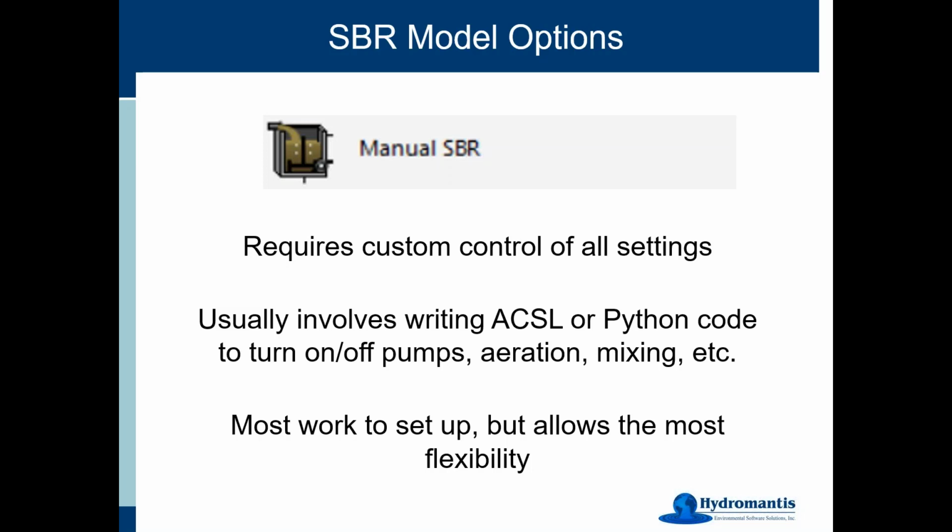The one time that I remember this was actually really handy was a particular project that I worked on that had 3 SBRs in parallel, and it flipped the loading back and forth between the top and the bottom one. And the one that was in the middle had a whole different schedule that involved taking overflow from the top and bottom ones, and it would flip back and forth, and flow went back and forth in different ways. And so we used a manual SBR and wrote a little bit of code to tell it how much to pump at any given time. And that all worked out pretty well.